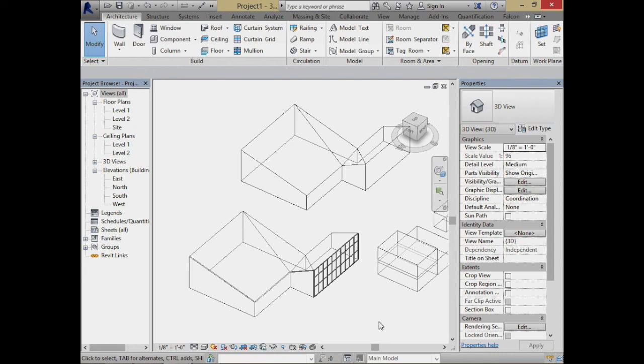For a typical building, do you have any sense of what the amount of actual total area is relative to the usable area? What tends to get added into total area is everything else: all those hallways, stairways, restrooms, utility spaces, and so on. They don't count in the usable area. So if you need 4,000 square feet of usable area, about how much real total square footage do you think you need? What do you think the overage is?